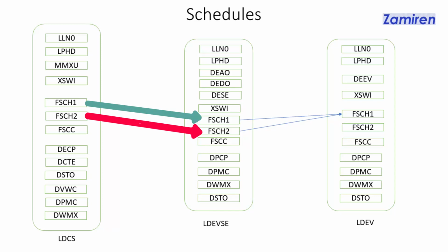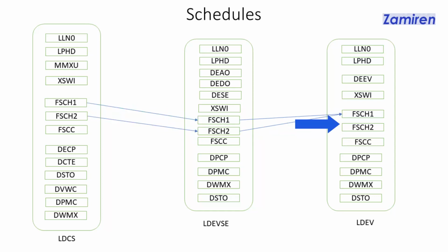When a vehicle plugs its cable into an EVSE, the EVSE sends it the schedule in service. When a change in the schedule in service is observed by the station, it sends this information to the EVSEs, which order the transfer of the in-service schedule into the connected vehicle's Schedule 1. The vehicle's Schedule 2 is reserved for a schedule managed by the vehicle, meeting the maximum value imposed by the in-service schedule.